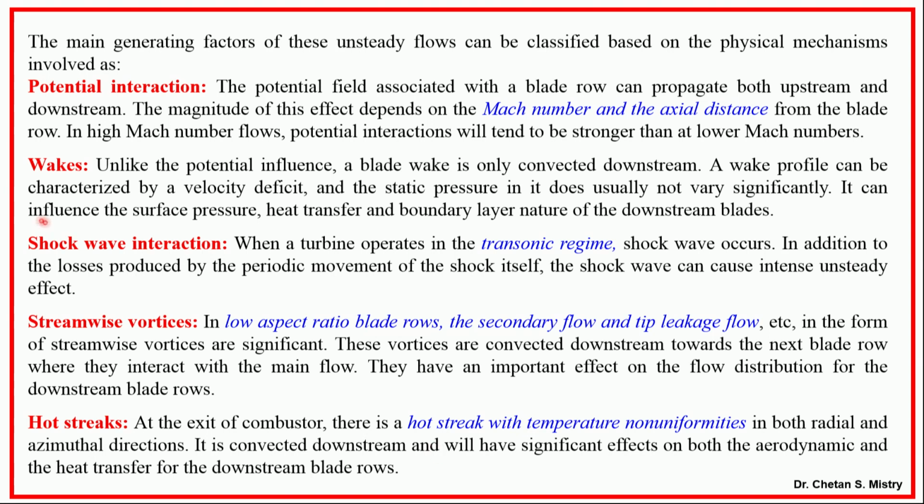Next, we define the wake. What is that wake? It is what is moving in the downstream direction. The wake profile is nothing but a variation of your velocity deficit. It can influence your surface pressure, your surface heat transfer, and your boundary layer behavior on the surface, which we talk about in terms of change of incidence angle. Then you will have shock wave interaction when operating in the transonic region, which generates unsteadiness in the flow.